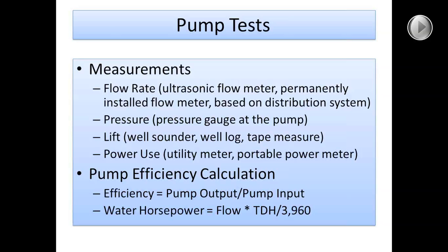We'll measure the pressure at the pump. If there's a pressure gauge, we'll use it. We'll usually install our own pressure gauge just to make sure that it's accurate.